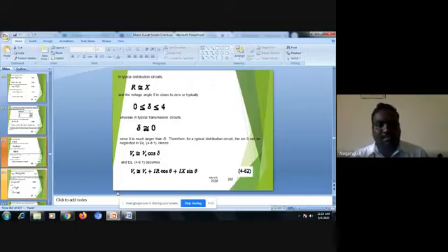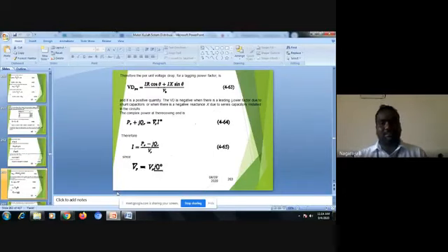Okay, Vs is equal to Vr plus Ir cos theta plus Ix sin theta, I'll get. So the voltage drop per unit is equal to Vs minus Vr, which is IR cos theta plus IX sin theta divided by Vb. That is the base voltage. So always this voltage drop per unit value is a positive quantity.